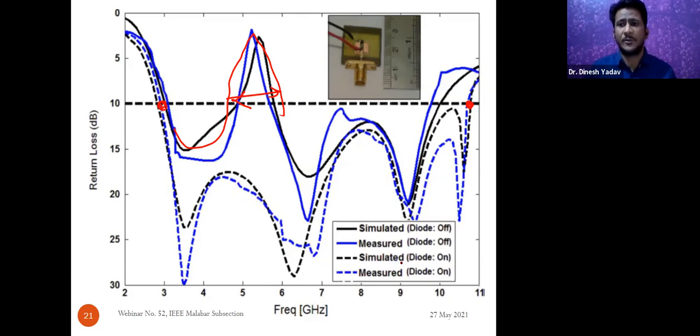So what we are doing, we are providing a band notch for that purpose, and this band notch is produced as a filter through the structure. That means this antenna is not radiating or receiving that band of frequency. This is the whole idea. So whenever a narrow band system is available in close proximity, you can't use that particular frequency for ultra wideband communication. But if in the close surrounding there is no narrow band system available, you can use the entire band.